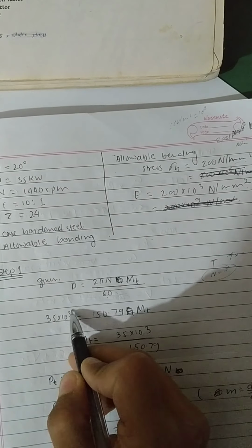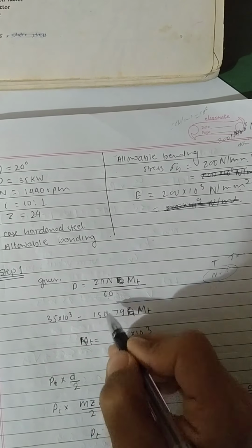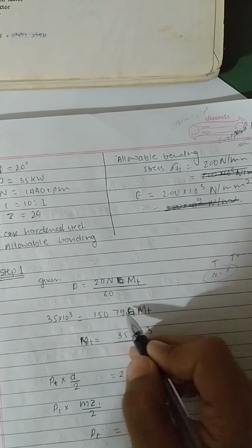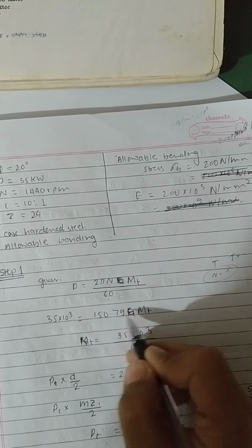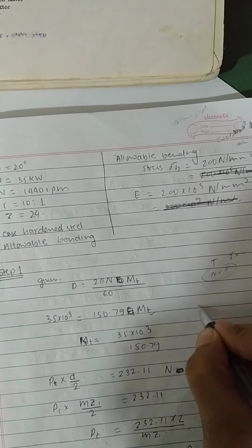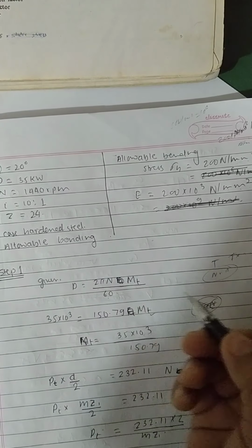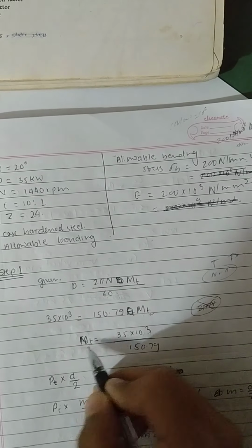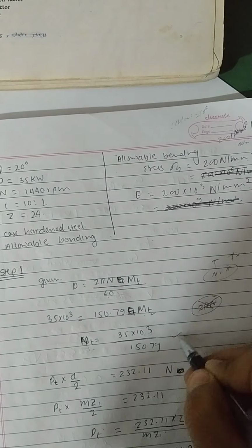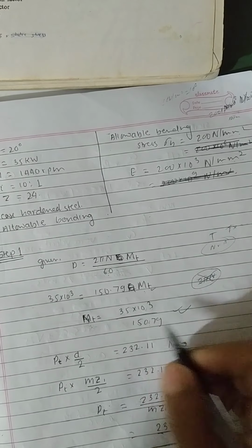And 35 into 10 to the power 3 equals 2 pi n Mt divided by 60, with n 1440. 2 pi n divided by 60 will give us 150.79. So Mt equals 35 into 10 to the power 3 divided by 150.79. You know that this is basic math. After that,